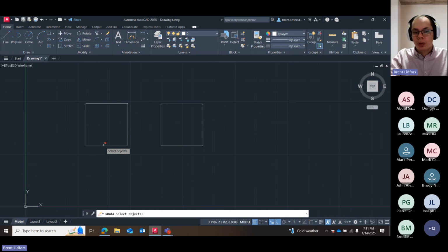But my one on the left here with the line tool, these are all separate objects. Okay, just something to keep in mind. We'll talk about how to join and explode. Those are the terms to join and separate line segments from objects. But that's later down the line. Don't worry about it for now. It's just making one object.